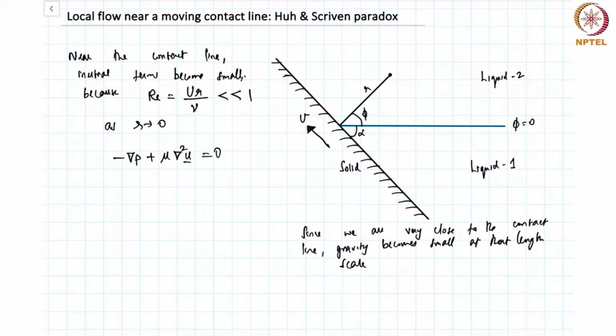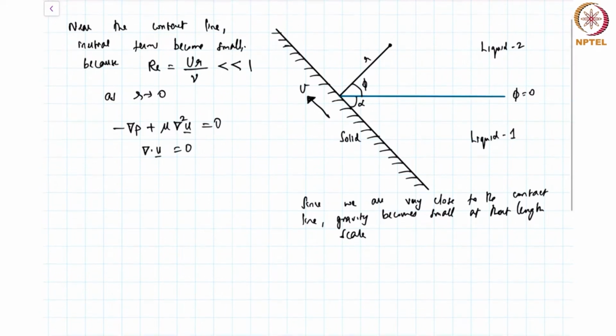If you say that these are my Stokes equations, and if you say that the fluids are incompressible, then you can eliminate pressure by taking the curl of this equation.